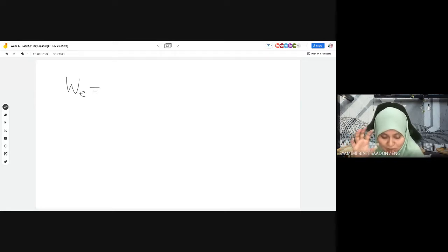Table A5 is to get the initial enthalpy H1, the table I gave two weeks ago. Once you get H1, you substitute it in the energy balance equation with the electrical work, heat loss, and all of this, and you will get H2 by calculation, not from a table yet.